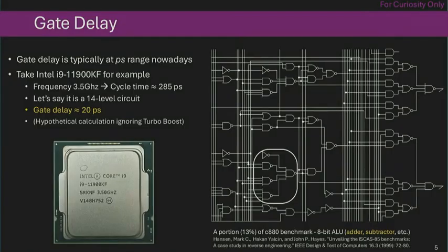All right. So timing analysis is dealing with the delay or latency of a circuit, also individual gates. So gate delay: every gate has a delay. For each and every gate, let's say we have a bunch of NAND gates over here, NOR gate, AND gate, it takes some time for us to go from inputs to outputs. When we put down some values at the inputs, the output doesn't get updated immediately. It takes usually a few picoseconds in current technologies.